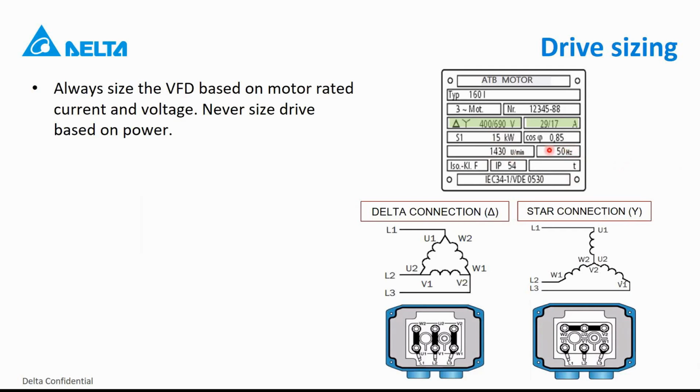But sometimes you get motors which are 8 poles or 16 poles or even 32 poles. In that case, the frequency is much lower, but the torque is actually a lot higher. And if you remember, I mentioned in the beginning of this training that the output current is actually proportional to the torque.